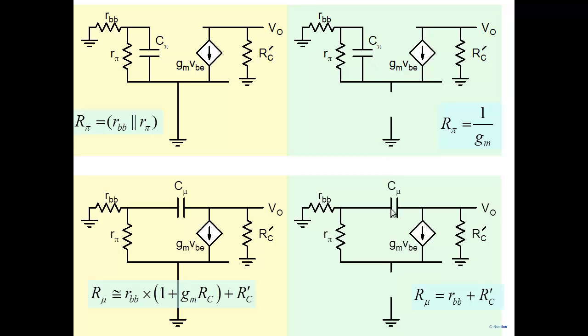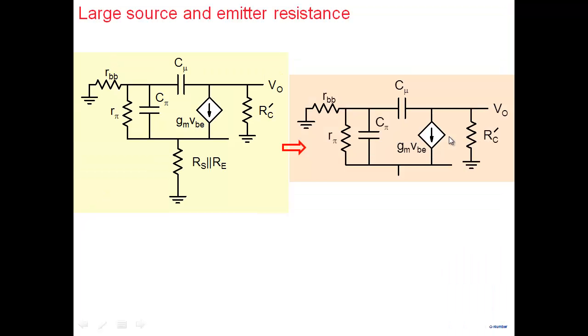And that's the reason why the time constants become small, and that's why you get a very high cutoff frequency. Now, these are calculations; you derive these relations from KVL and KCL. Think about why the frequency response is becoming large. I'll leave that for you to think about. What is the real reason, when I make an open circuit, why is the resistance becoming small here?